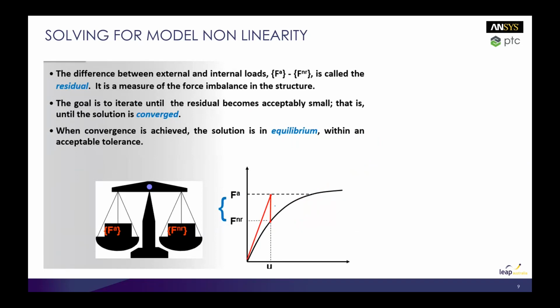Okay, so this difference between the externally applied loads and the internally generated loads is called the residual. This will never ever be zero because of computer precision. So we say that the solution is in equilibrium when that's within an acceptable tolerance.